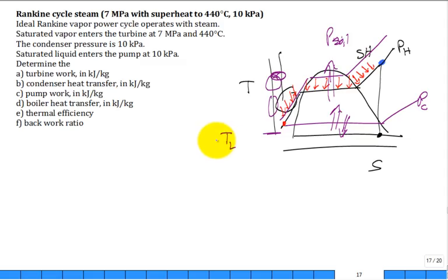So if I want a lot of entropy to go with a small amount of Q, make TL low. It throws away a lot of entropy for the same Q. Just like if I want to bring in as little entropy as possible, make TH high. And if I want to throw out as much entropy as possible, make TL low.